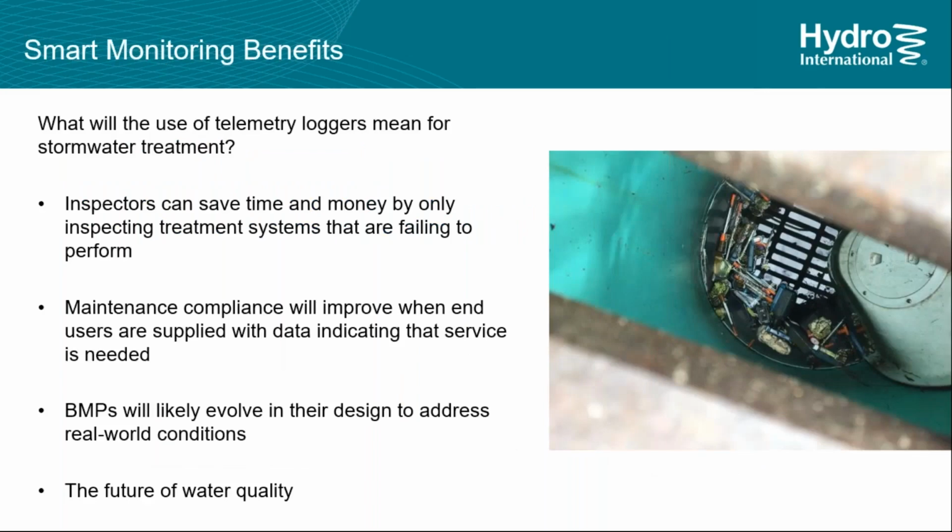And so what would the benefits of this be? You know, you're no longer sending inspectors to site. Imagine if every BMP you put in the ground, you had a website you'd go to, and if it was showing a red dot, it meant its sump was at 75% capacity or greater, and if it showed in green, it was 75% or less.